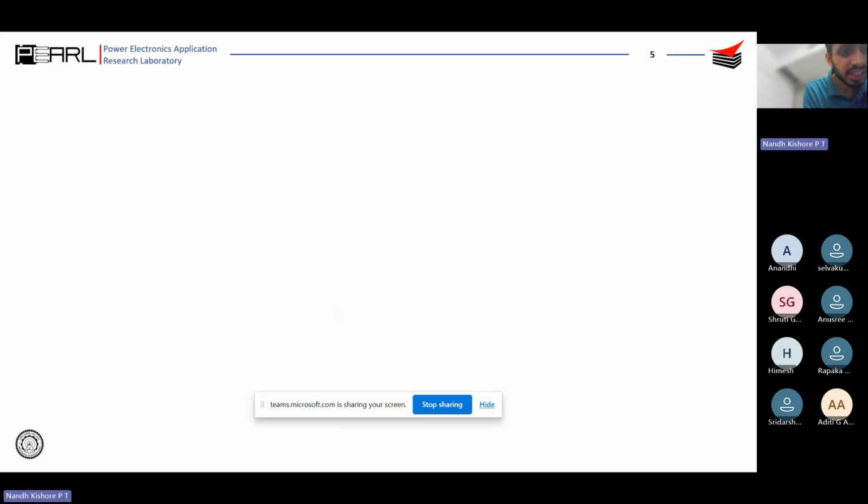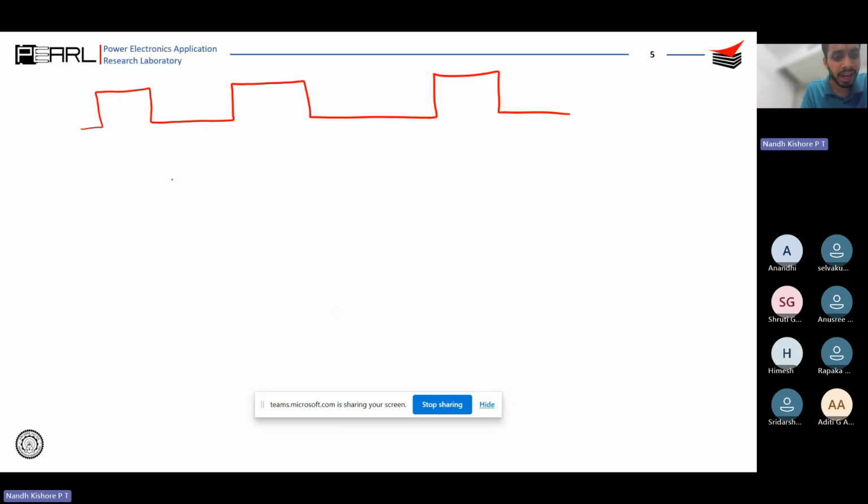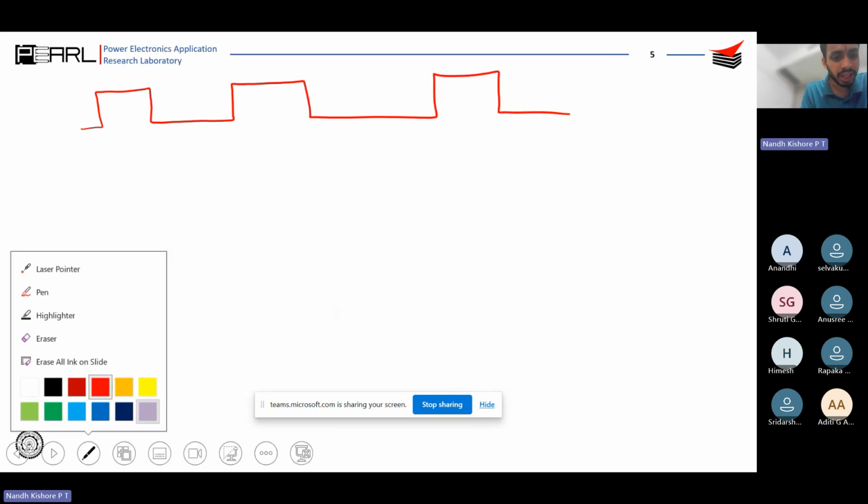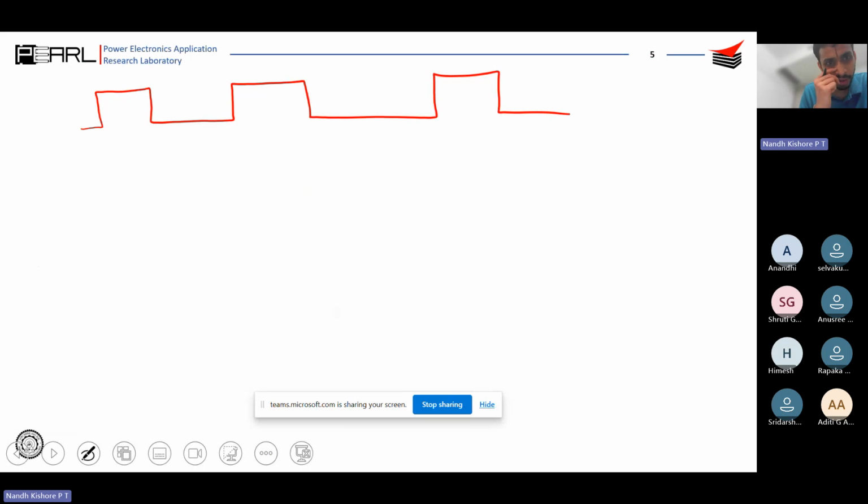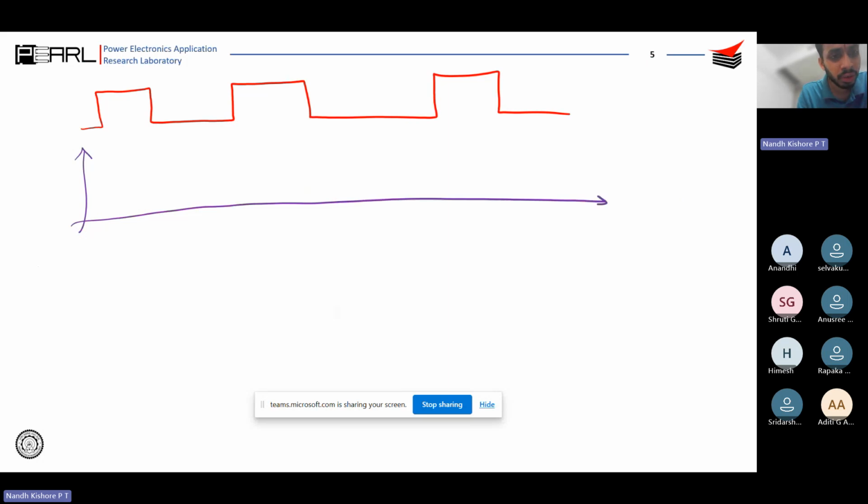So we were just saying that a device is going to be on and off, something like this. I'm not going to go deep into it, but in a buck converter, how would the inductor current look when the device is on? The inductor current is going to be something like this, and when the device is off, you get an inductor current something like this, in steady state of course.